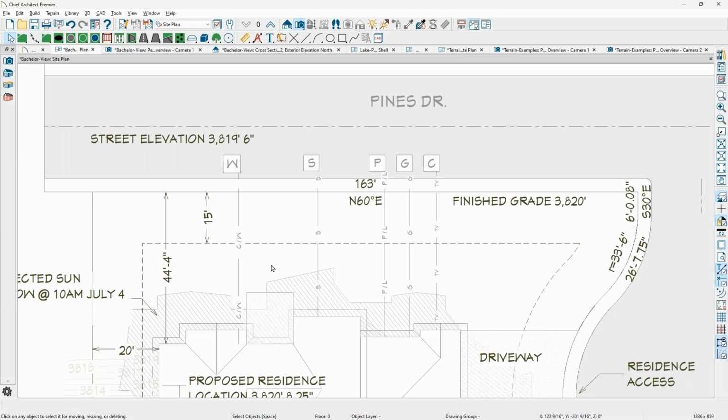And I'm sorry, I missed that. How would I show a pipe? Do you actually want to see it in 3D? I would, yes. So what I would do is take one of these lines and convert it to what's called a molding polyline. So I've selected the line for the water here, right? Yeah. And then there is a convert button in my lower edit menu, and it says convert to polyline. I'll pause there. Do you see it okay? I do, yes, thank you. It was Alex, right? Yes.